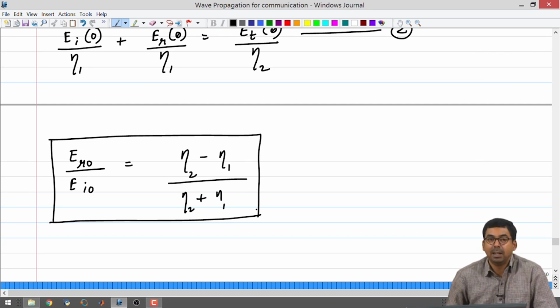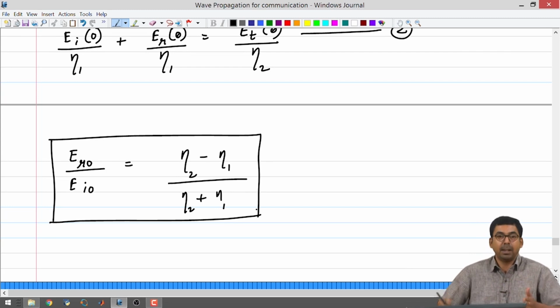It looks exactly like the reflection coefficient in the transmission line. So, for normal incidence on an interface, when you are assuming that there is no flip in the electric field and all that, it is exactly analogous to transmission lines. So, it is fine for you to assume that everything is a transmission line and then join the pieces together, and you may arrive at similar deductions.